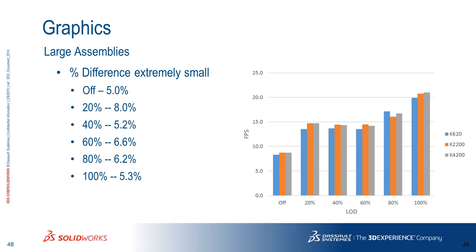Okay? That's unfortunate, right? But when that depth of the assembly combined with the number of components reaches some threshold that we have not yet identified, SolidWorks slows down, it gets more inefficient in delivering the information to the graphics card as to what to paint. And we see some dramatic results in that. So what ends up happening is regardless of what video card you have, SolidWorks becomes the choke point then, and across the board, they all perform identically.